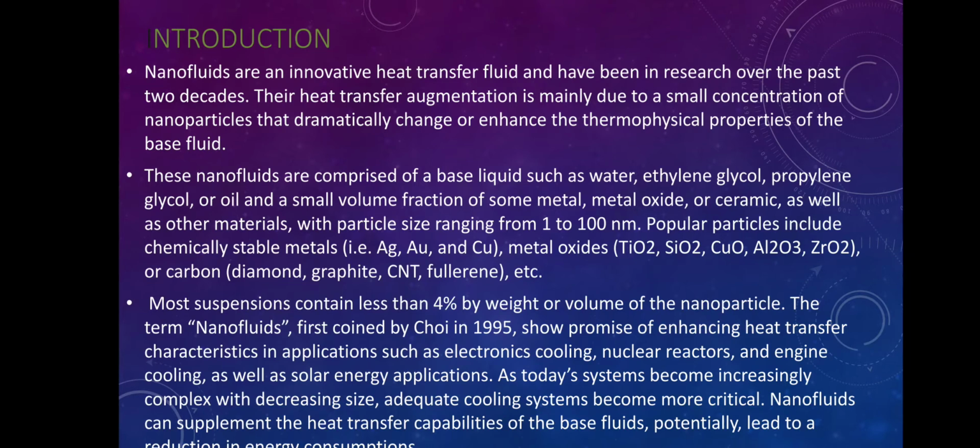Popular particles include chemically stable metals, that is silver, aluminum and copper, metal oxides or carbon, etc. Most suspensions contain less than 4% by weight or volume of nanoparticles. The term nanofluid, first coined by Choi in 1995, shows promise of enhancing heat transfer characteristics in applications such as electronics cooling, nuclear reactors and engine cooling, as well as solar energy applications.